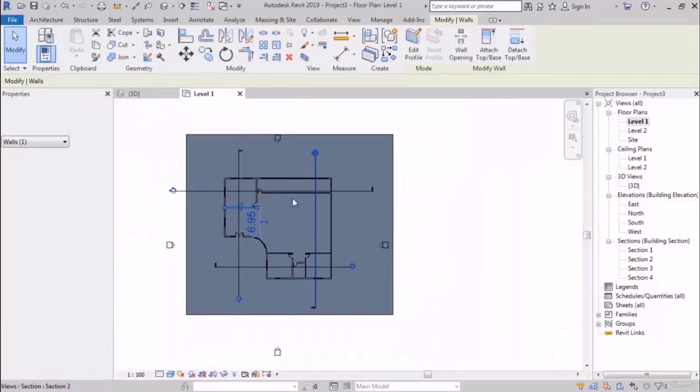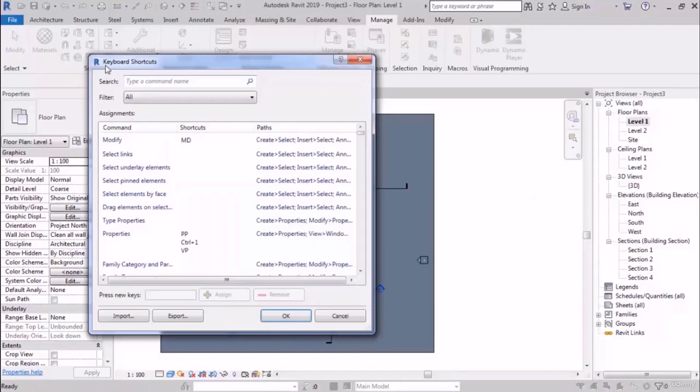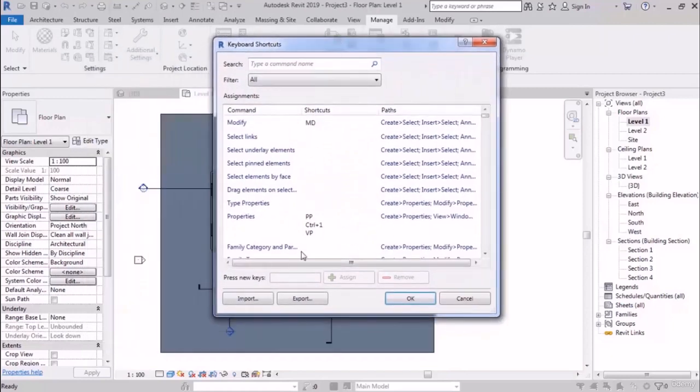And the ultimate point, so that you can go and practice after that, is the management of the shortcuts. In Revit, all the shortcuts include 2 letters, like WT, TW, UN. You can also create a shortcut for commands that don't have one, or even change the shortcuts if you like. So if you press KS, which is for keyboard shortcuts, you can manage your shortcuts in Revit.